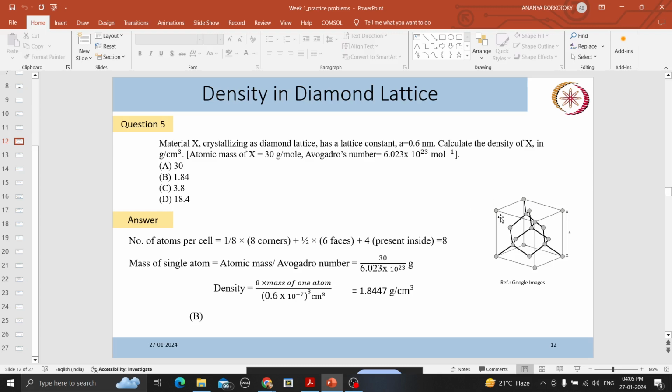So how were you determining this? You are dividing the whole volume by 1 by 8. Like that you can determine the atomic density based on the area of the atom and the shared area between two planes, right? So you can determine the atomic density in the plane and divide by the area of the plane, and that's how you can determine the atomic density for silicon in the 100 plane and 111 plane.